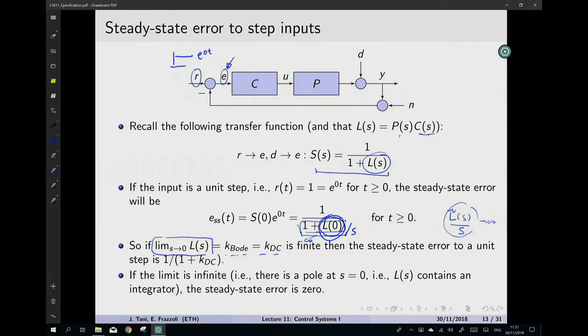So if you have a constant steady state error, but you integrate that steady state error, then it gives direct information to the controller that it needs to take action in order to reduce it. So integrating a constant value will let us eventually drive the steady state error to 0.